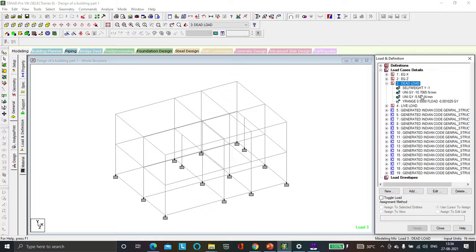So in order to know which frequencies are safe for that building, we need to know the natural frequencies of that building, which depend on the properties of the building and the self-weight of the building. So Staad Pro also can analyze dynamic analysis of structures using the mode analysis method.